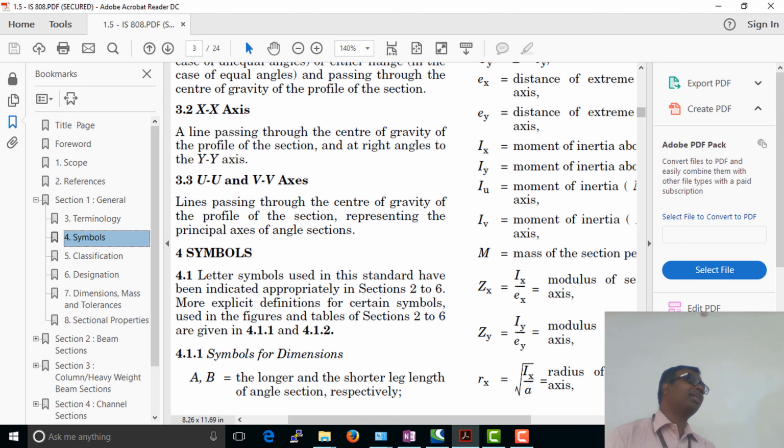It is the distance of the extreme fiber in compression. Okay, so you are looking at a compression fiber in steel, in concrete, only because concrete can only take compression. How much tension can concrete take? Negligible. Zero, yes. From a design aspect, it is zero. So negligible that you can even take it as zero. Both of your answers are perfectly right.